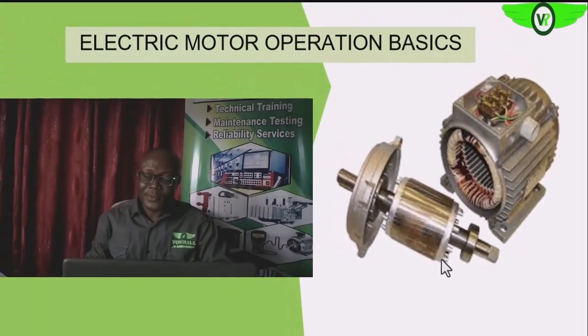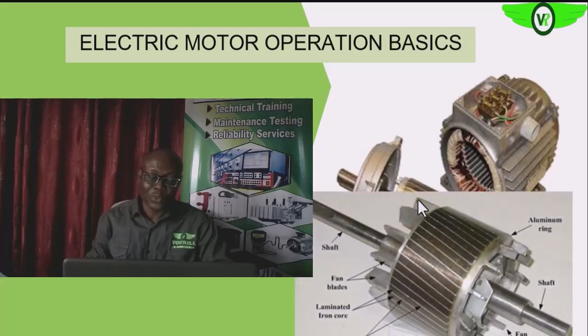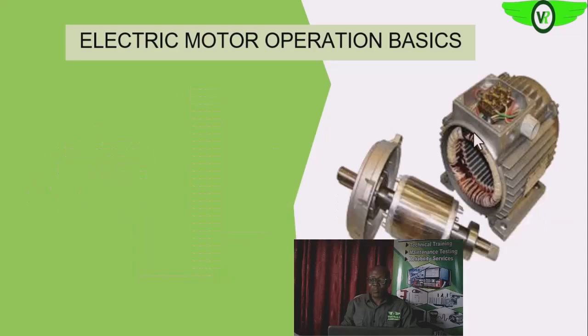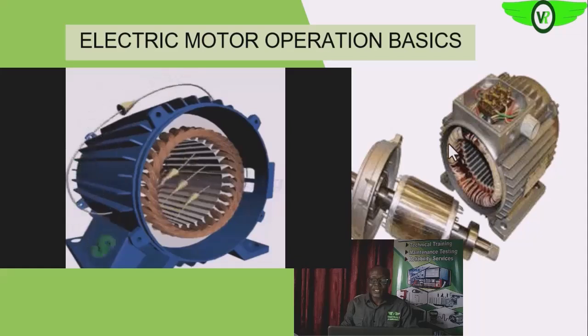Now remember that when you connect the electric motor to your three-phase supply, it means that you are sending voltages that are displaced by 120 electrical degrees from one another, the 3 phases, into this stator winding. That will end up magnetizing the stator winding.